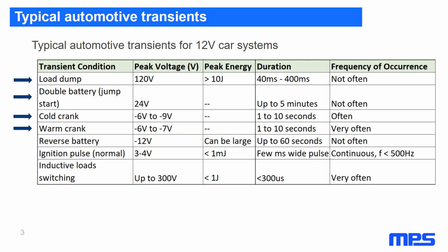Warm crank is similar to cold crank, although not as extreme. The voltage will dip about 6 to 7 volts from nominal battery voltage. And the duration is typically shorter, but could last up to 10 seconds. And this condition occurs very often.